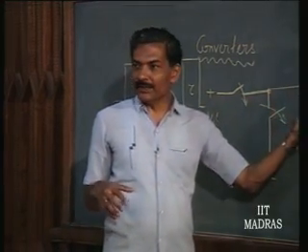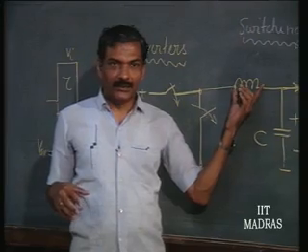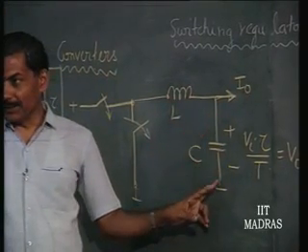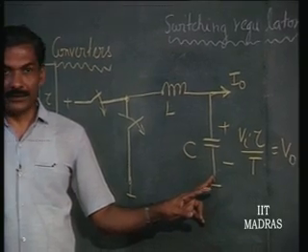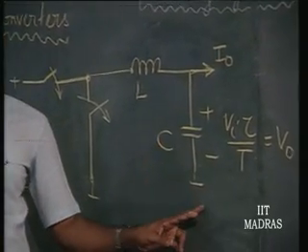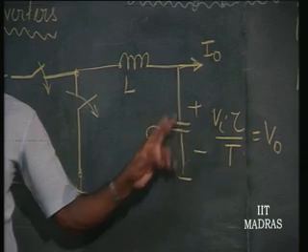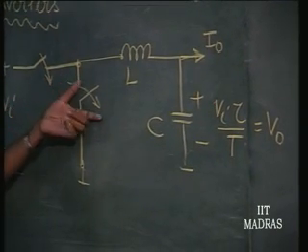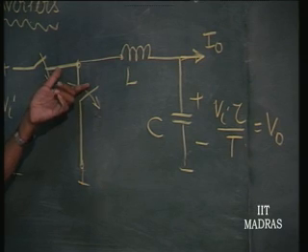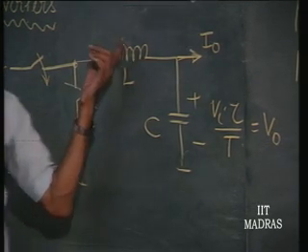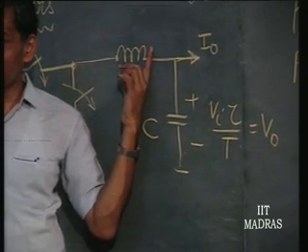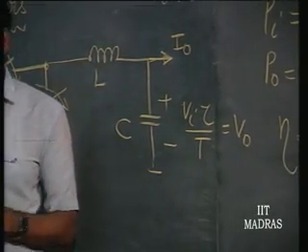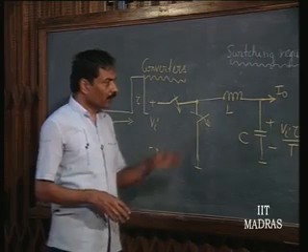There is going to be some DC resistance or AC resistance here, which is going to cause a certain amount of power dissipation. There is going to be a leakage resistance here, which is also responsible for a certain amount of power dissipation. The primary power dissipation in switched power regulators occurs in the switches when they are on, and in the inductor because of its finite resistance. The rest of the power dissipations are negligible, the components being small. Now how do we analyze this?